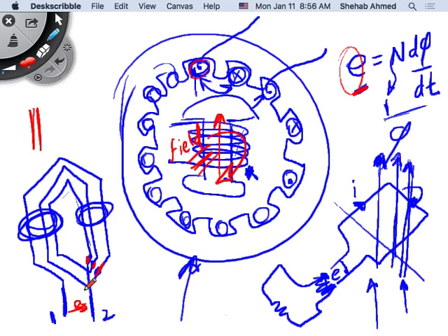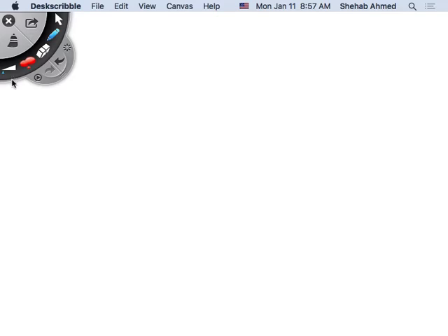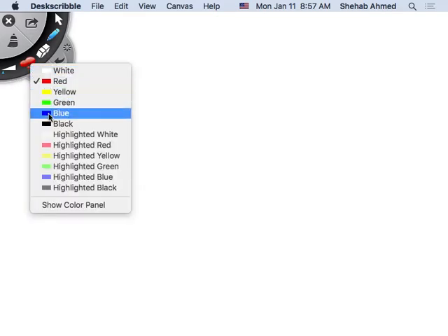It's much easier than taking a rotor out of a stator and shutting down your whole plant and all of that to do it, right? And transformers would be cheaper devices than a generator, right? So that's why we have to step up. And this whole discussion is about why we step up, right?